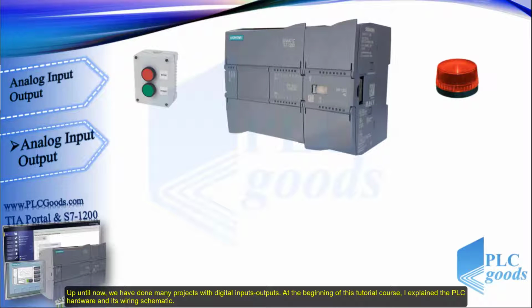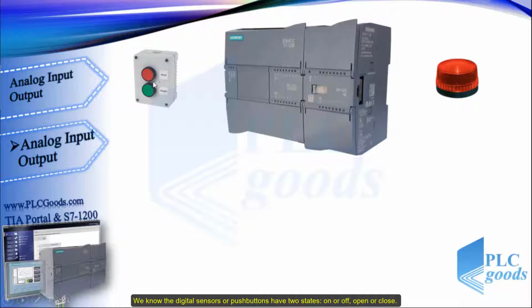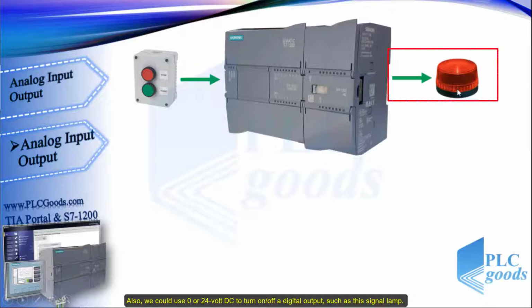Up until now, we have done many projects with digital inputs/outputs. At the beginning of this tutorial course, I explained the PLC hardware and its wiring schematic. We know the digital sensors or push buttons have two states, on or off, open or close. These instruments use 0 and 24-volt DC to send their on-off states to the PLCs. Also, we could use 0 or 24 volts DC to turn on/off a digital output such as this signal lamp.